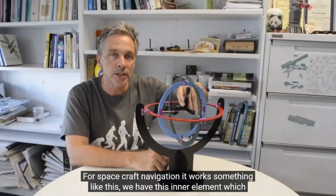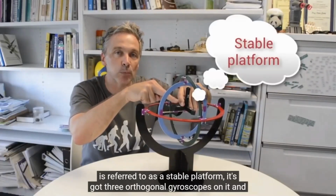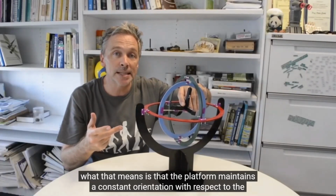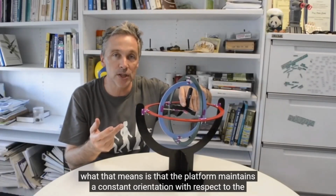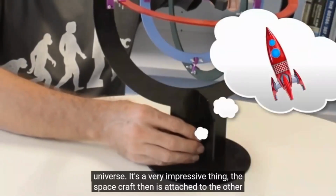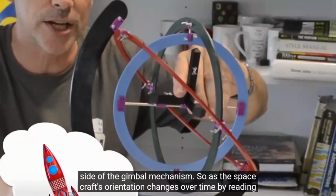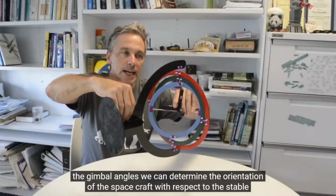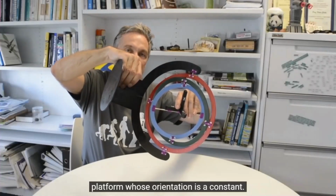For spacecraft navigation, it works something like this. We have this inner element, which is referred to as the stable platform. It's got 3 orthogonal gyroscopes on it. And what that means is that the platform maintains a constant orientation with respect to the universe. It's a pretty impressive thing. The spacecraft then is attached to the other side of the gimbal mechanism. So as the spacecraft's orientation changes over time, by reading the gimbal angles, we can determine the orientation of the spacecraft with respect to the stable platform, whose orientation is a constant.